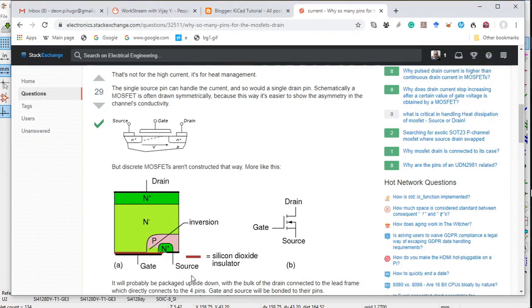That's why a transistor has multiple source pins, so that heat can be conducted out of the transistor and it stays cool. One must also remember that these MOSFETs conduct high currents, and multiple pins lower the electrical resistance, which facilitates the flow of current through the MOSFET transistor.